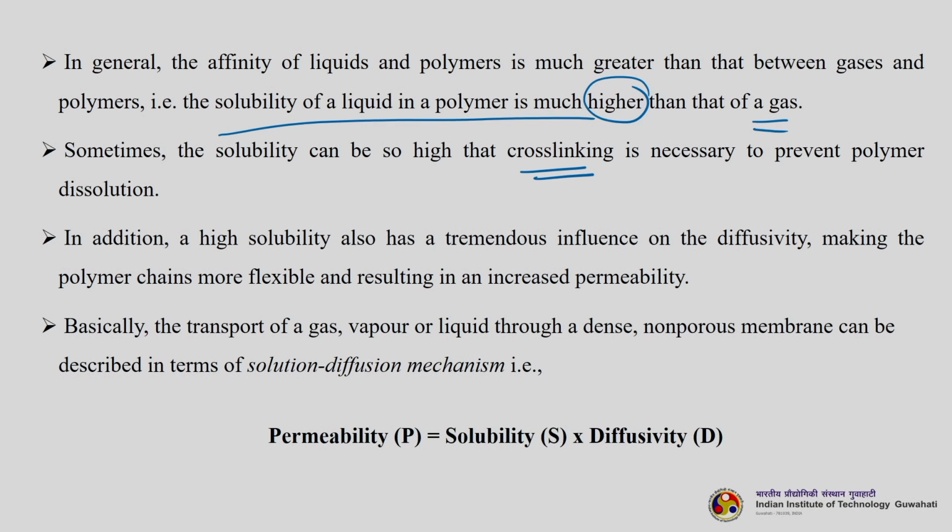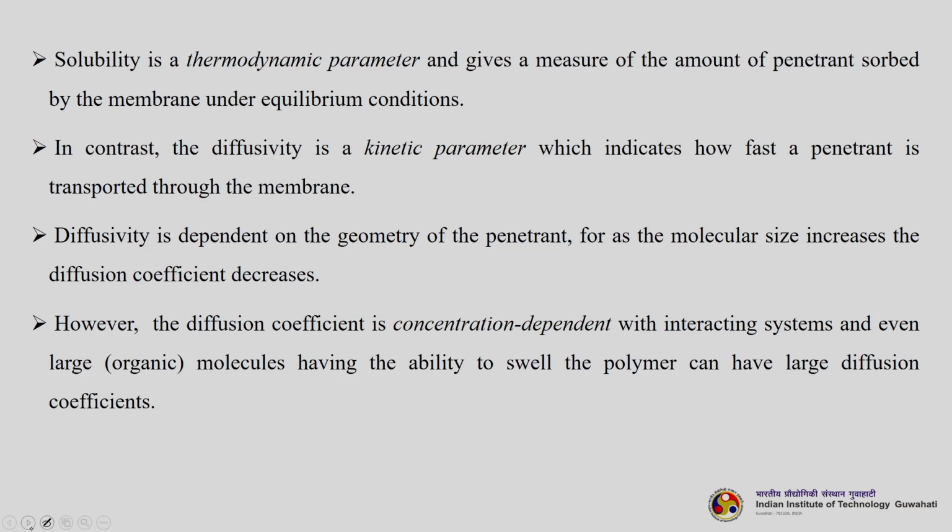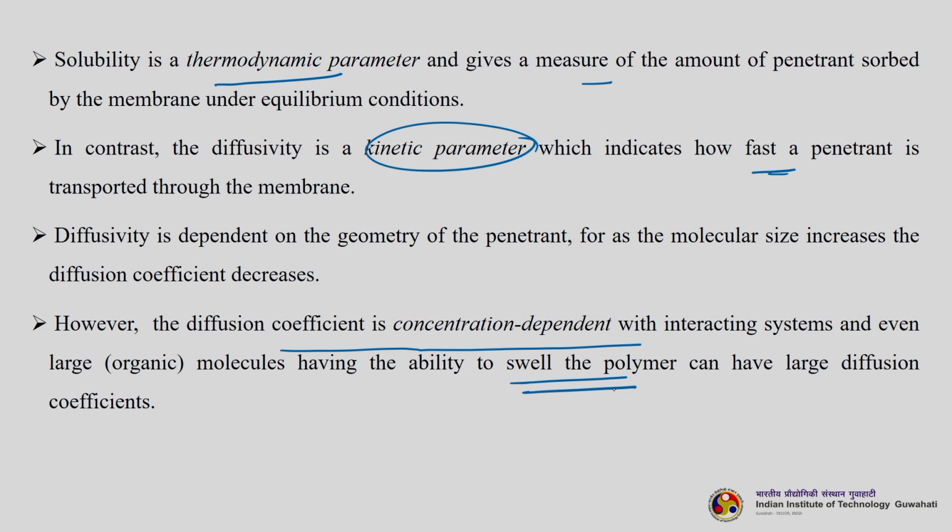So, basically the transport of gas, vapor or liquid through a dense non-porous membrane can be described in terms of solution diffusion. So, permeability equals solubility times diffusivity. Solubility is a thermodynamic parameter and gives a measure of the amount of penetrant sorbed by the membrane under equilibrium conditions, whereas diffusivity is a kinetic parameter which indicates how fast a penetrant is transported through the membrane. Diffusivity depends on the geometry of the penetrant: as the molecular size increases the diffusion coefficient decreases. However, the diffusion coefficient is a concentration dependent term, and even large organic molecules having the ability to swell the polymer can have large diffusion coefficients.